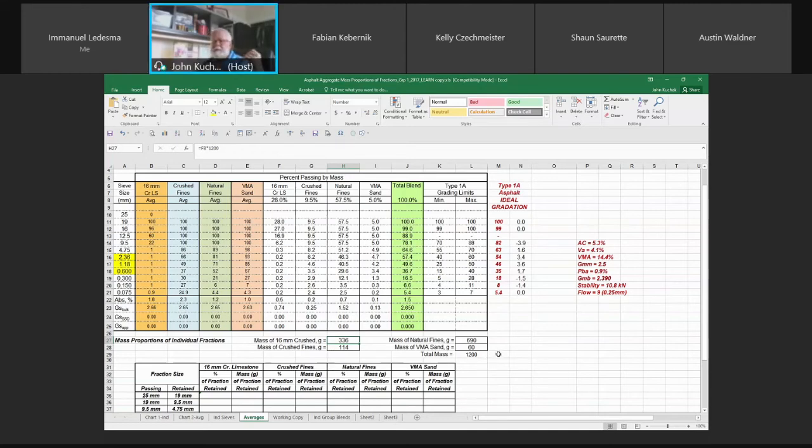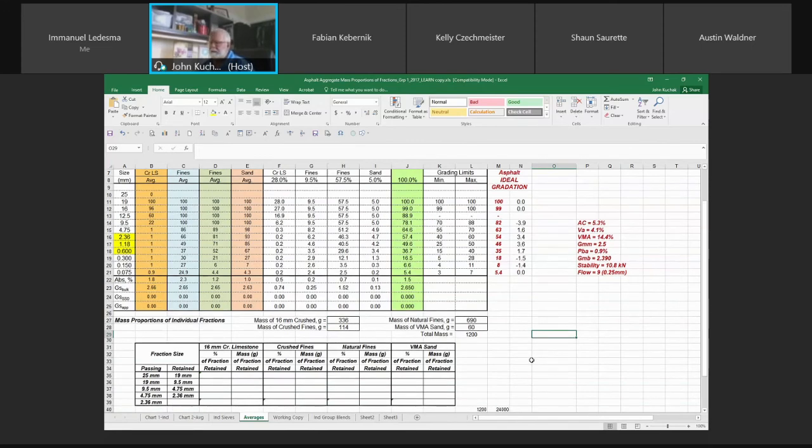When you're designing for Winnipeg streets, we're using 75 blow Marshalls, really densifying it. I've done projects for Transport Canada for the runways in Winnipeg. They only use a 50 blow compaction, so the densities won't be as great. But again, they're looking at volume of traffic and the loads, the thickness of the mix too. So all this comes into consideration when you look at the fundamentals of asphalt design. We're not going to cover too much of that, we just don't have the time.